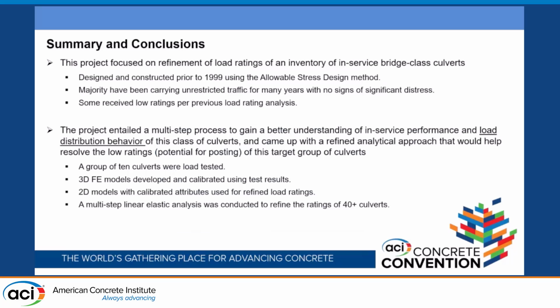So with that, this is just the summary and conclusion. The project focused on the refined rating of a specific class of culverts that were designed based on the ASD method. They were in service for many years without any restriction on traffic and no sign of distress. But recent rating based on the modern code requires load posting on them. We proposed this multi-step process that includes load testing and refined analysis to gain a better understanding of load distribution in these types of structures, and essentially we help the owner avoid posting on these types of bridges. Thank you very much.